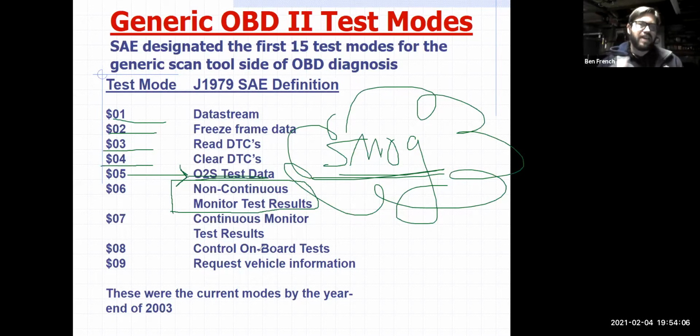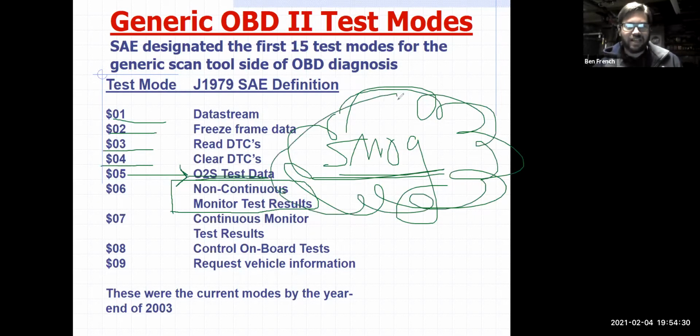So things like your catalytic converter, if I can test that, and I can test the EGR valve, and I can test the EVAP system, and I basically can test the vast majority of the emission control devices on my car, and they all test good, and the engine is running well, guess what? The emissions coming out the tailpipe, the smog, should be low. And so that was kind of the idea. So mode 6 is non-continuous monitors, things like the catalytic converter test results.